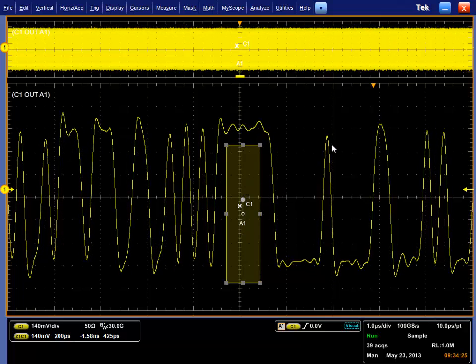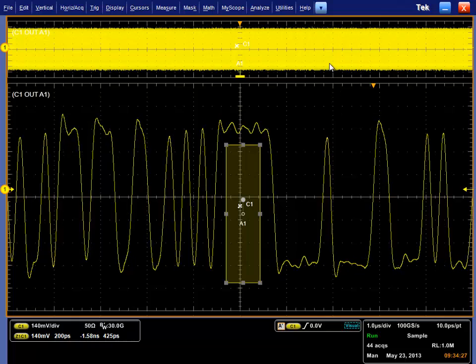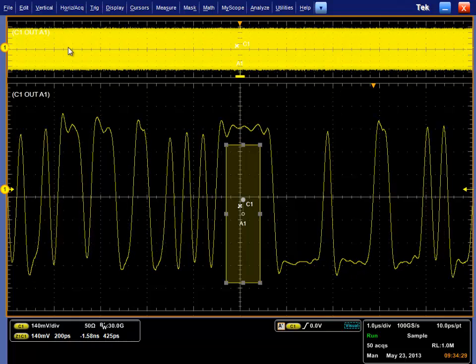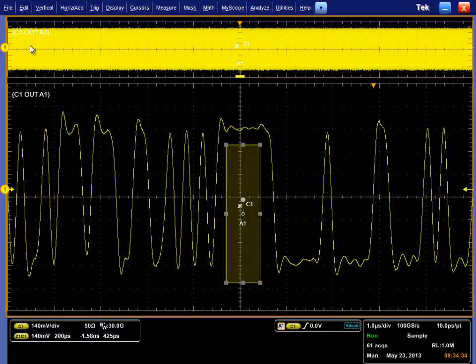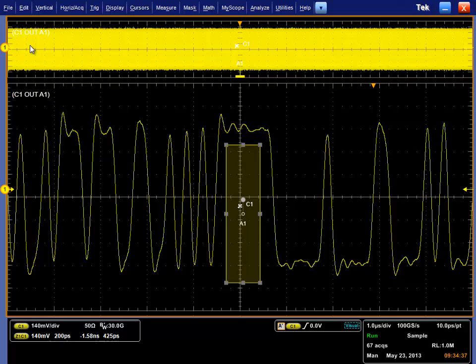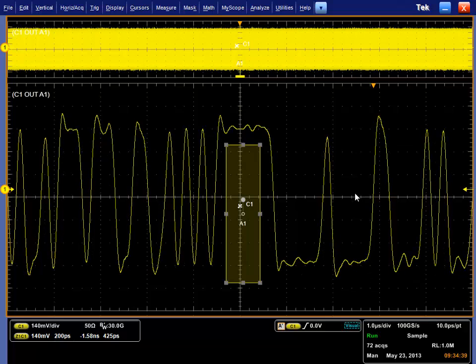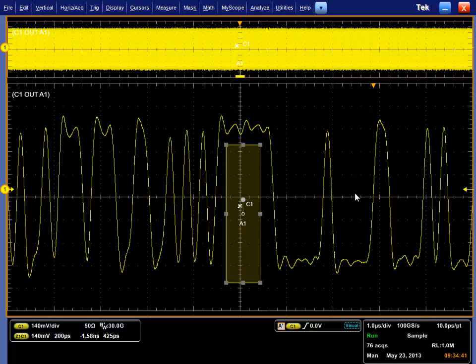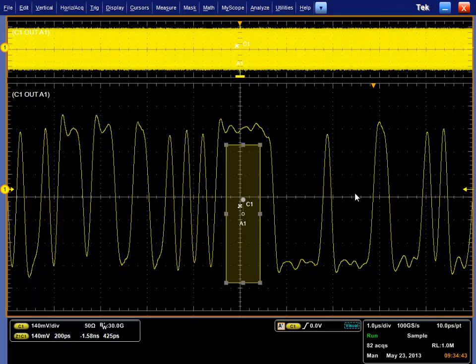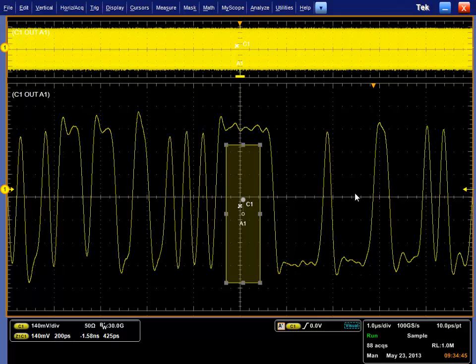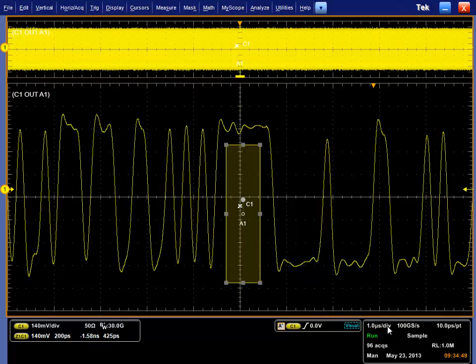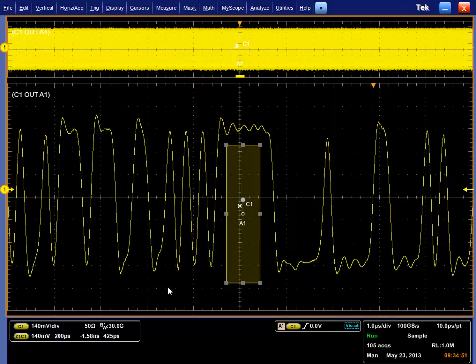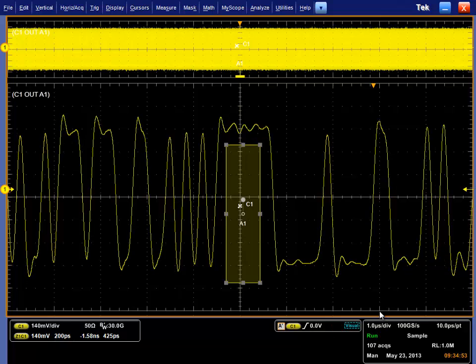One thing you want to do whenever you look at a high-speed serial signal is capture a decent duration. You'll notice all oscilloscopes now have long records. We're going to do a 1,000,000 point record for a demonstration, but if you're doing debug on your systems, you may need to do 20 or 50 million point records to capture the low frequencies. 1 over the duration of your capture is the lowest frequency you can see. So when you're debugging, you need to keep that in mind.